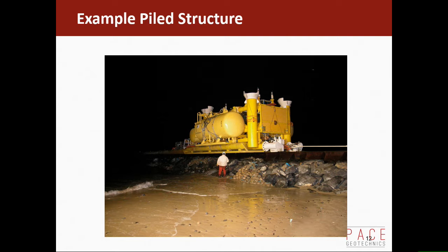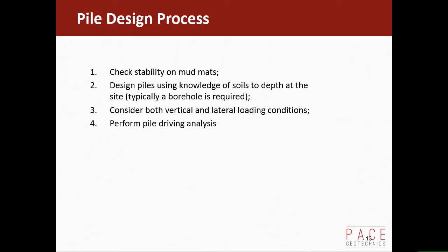Getting the mud mats right for the structure can be difficult on soft clays because you've got a limited capacity. But once it's piled, it's fine. And ultimately the real reason for putting piles in on that structure was to allow for fishing gear loads, snag of fishing gear. So the design process is essentially check the stability of the mud mats, design the piles using the knowledge of the soil's depth at the requirement.